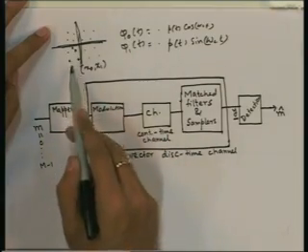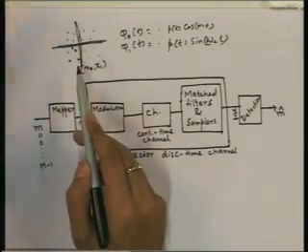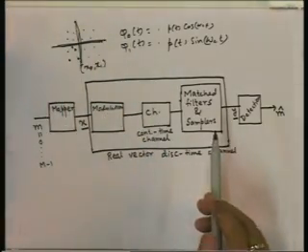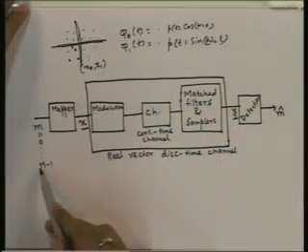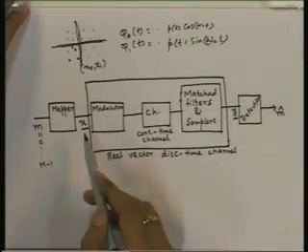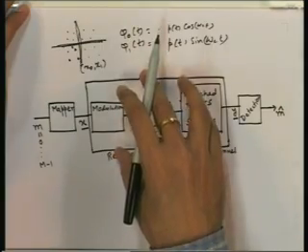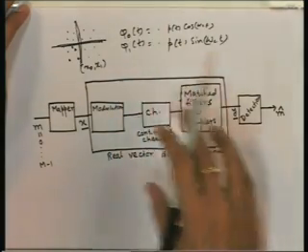So, we need not take 16 QAM, we can take 8 PSK, we can take any other constellation we want, which will have less probability of error ultimately. So, we can still design these things, and we can design M also. M also can be changed, M is not inside. So, we can consider this channel, and there is